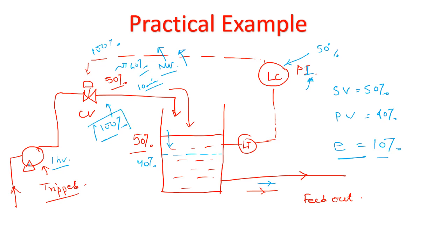So now what is the problem? This is the situation, this is the reset windup situation or integral windup situation. So what is the issue with it? Yes, the valve is opening 100%, but what is the issue with it? Suppose after 1 hour, the pump gets rectified, and the pump starts again. Pump again starts giving the flow.